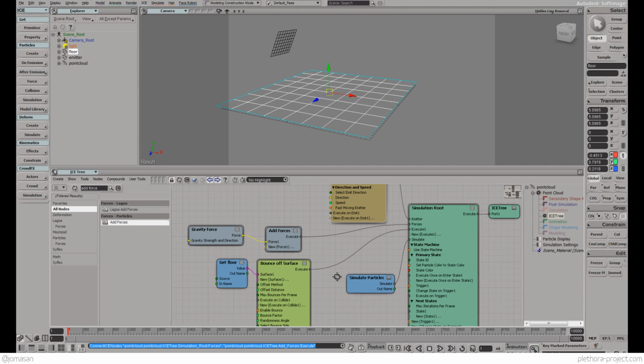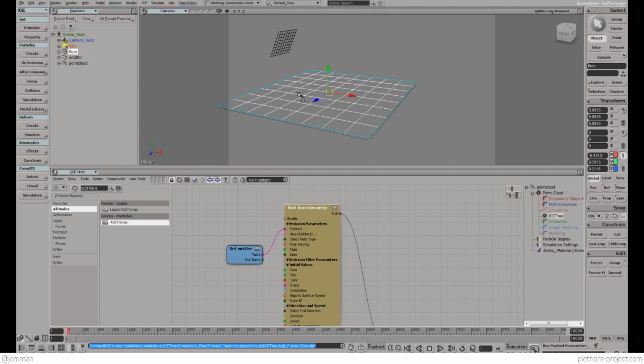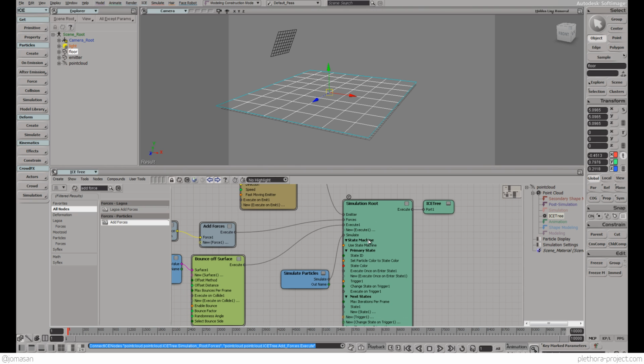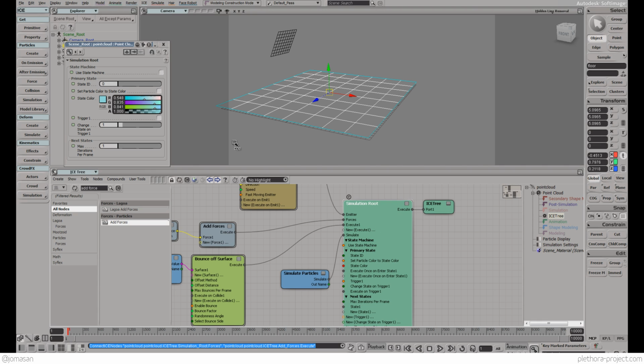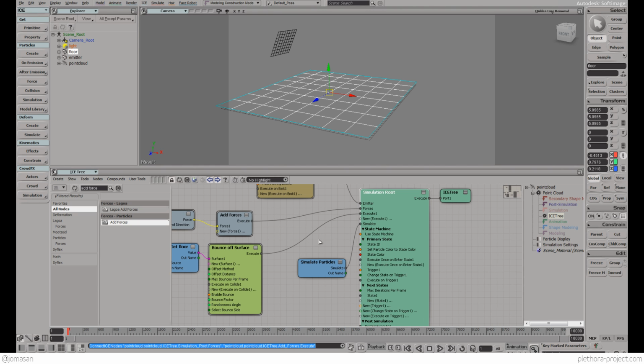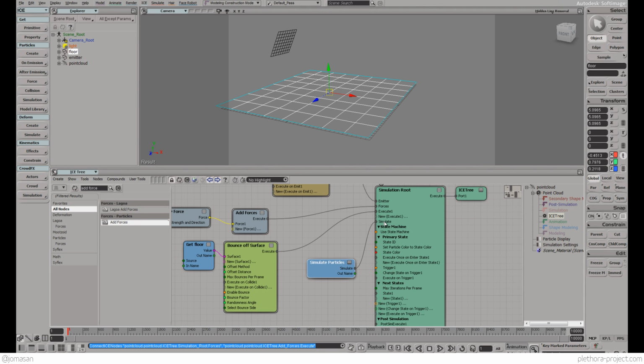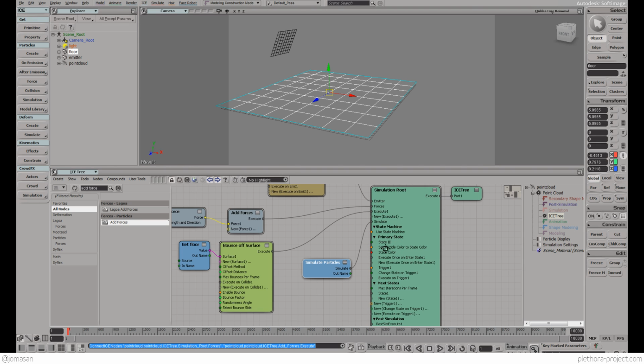So basically, what we have here, this brown one, is the emit from geometry node, which is saying how these particles are getting emitted from this surface. So this surface becomes the emitter. That's been done for us. The simulation is how that simulation works. We could use states, something that we're going to see later, like a state machine for behaviors of particles. Right now we're just using emitters, forces, and the execution for additional elements that we want to calculate, like the bounces, and the simulation of particles gets activated after that, right? So we're calculating all these elements together, and we get the result.